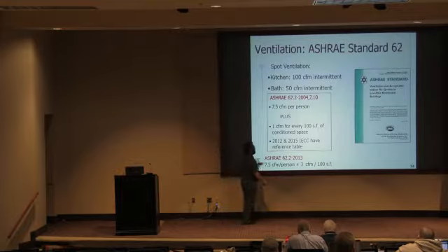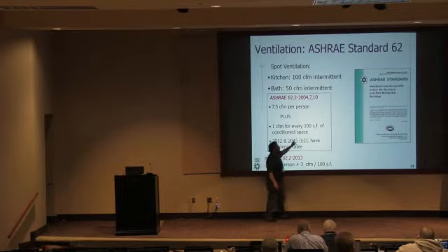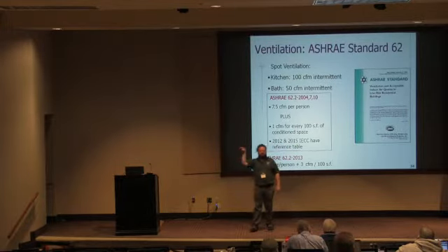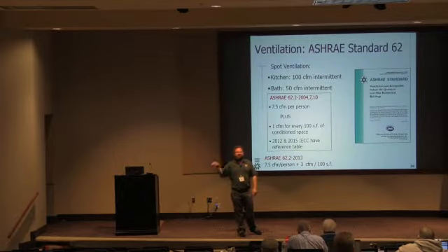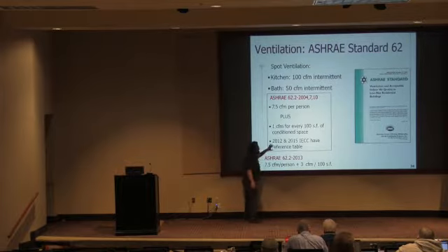And it just says they have to do ventilation, and it has a reference table, which is basically the ASHRAE equation. And you look up your number of bedrooms, and you look up your square footage, and it tells you how many CFM of ventilation area you need in your home. And it's really simple and straightforward. So that is a nice thing that is in the new cycles of the code.